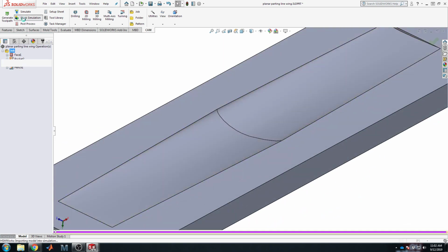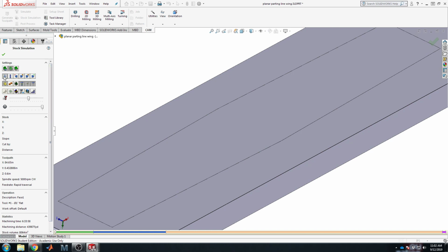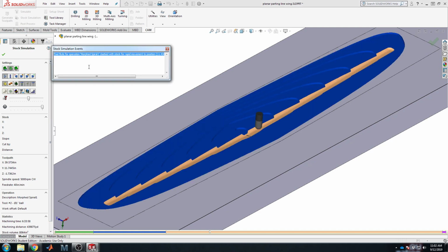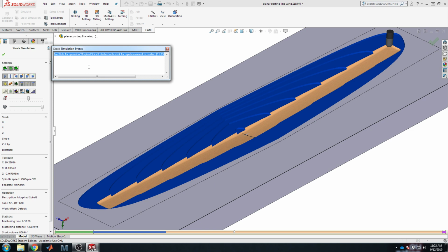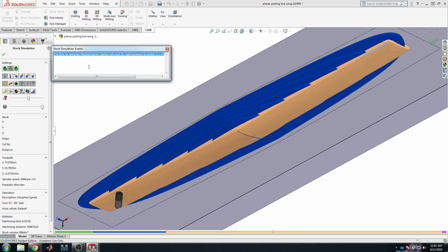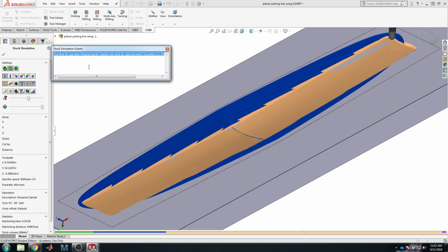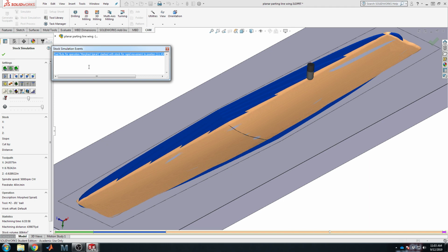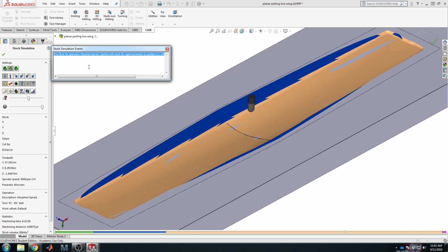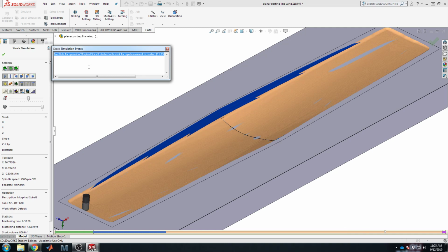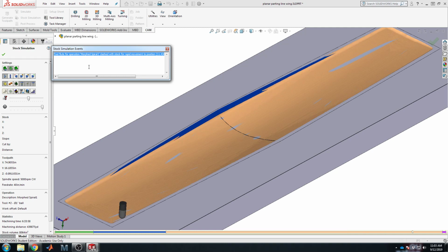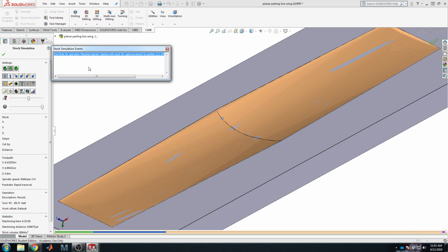So let's do the whole job simulation. Do one last simulation here. Run it. So that smaller step over took the cut time back up to 6.5 hours, as you'd expect. But look how smooth the surface is coming out. The other downside of this is that, especially with some lower reliability machines, if power cycles during the 6 hours, or if machine breaks, or if it misses steps, if anything goes wrong in 6.5 hours, then it probably ruins the whole part.